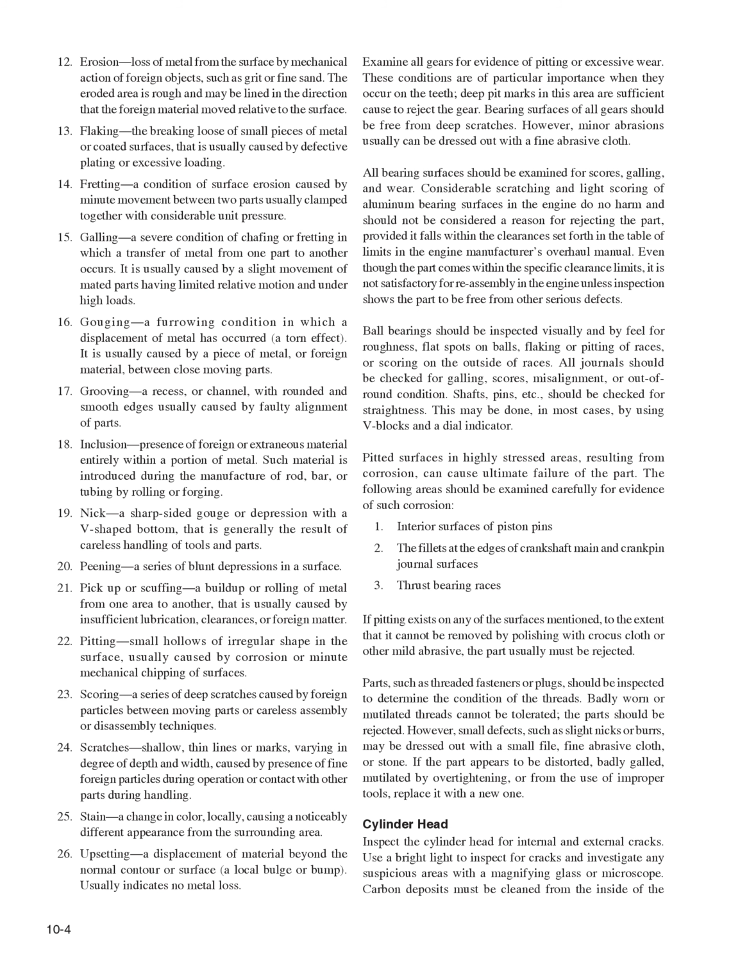Pitted surfaces in highly stressed areas, resulting from corrosion, can cause ultimate failure of the part. The following areas should be examined carefully for evidence of such corrosion. 1. Interior surfaces of piston pins. 2. The fillets at the edges of crankshaft main and crankpin journal surfaces. 3. Thrust bearing races. If pitting exists on any of the surfaces mentioned, to the extent that it cannot be removed by polishing with crocus cloth or other mild abrasive, the part usually must be rejected.